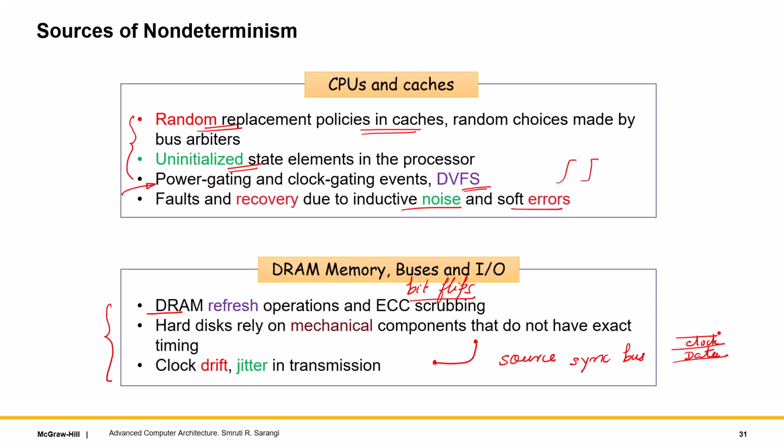So because of these little one or two cycles here and there, you cannot really debug a chip cycle by cycle, right? And then what can happen is that maybe there will be some fault which gets activated in some rare corner case. Let's say that you are expecting some operation to complete in 3 cycles, but it somehow takes 4. Then you may have a bug, a problem, but next time you try to reproduce it, every single time you'll get 3. You will never see a 4. So this makes the process of post-silicon verification and debugging quite tough. And the reasons are all mentioned here.